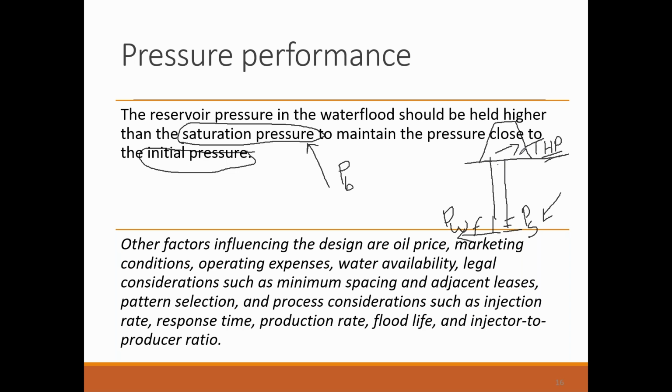And if your tubing pressure is on the higher side, you definitely have to do a workover, kill the well, and only after that can you replace your wellhead. So I want you to concentrate on how significant this can be. Just by looking at a particular valve or gauge, you can take a major decision in well operations and prevent some unsafe practices.